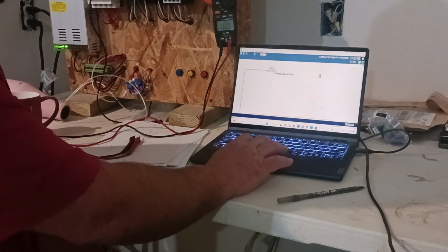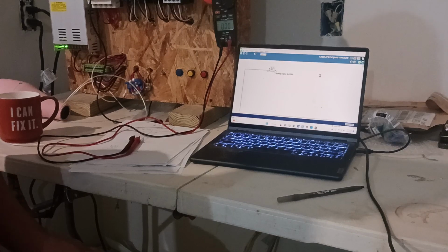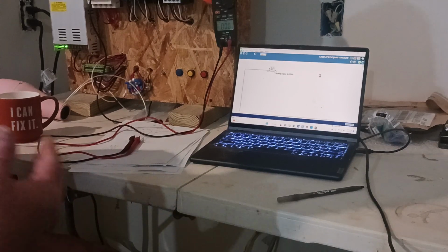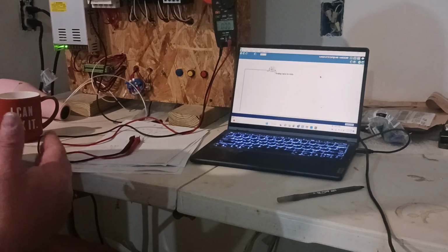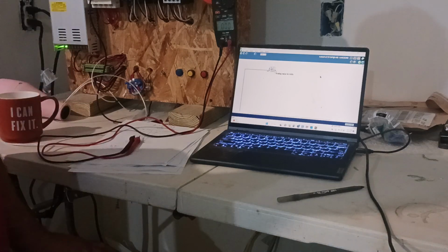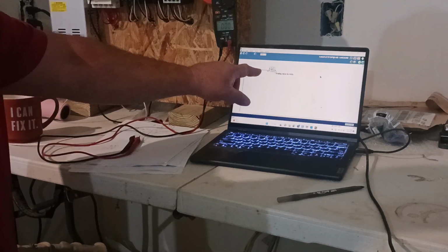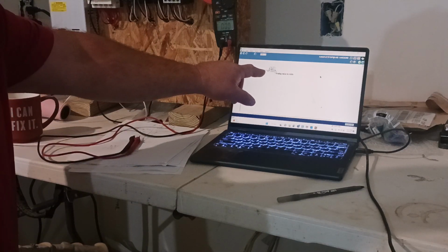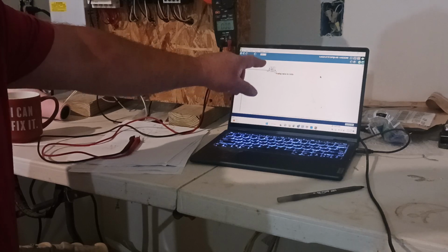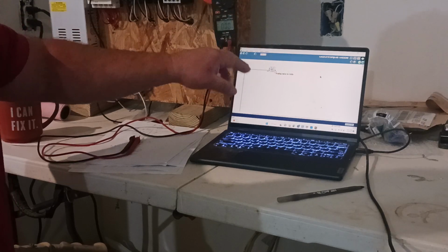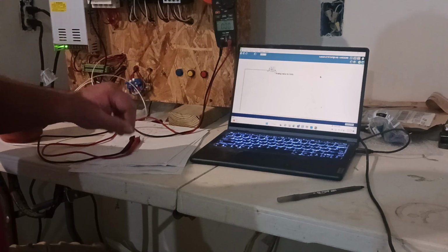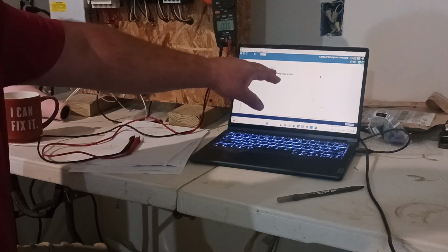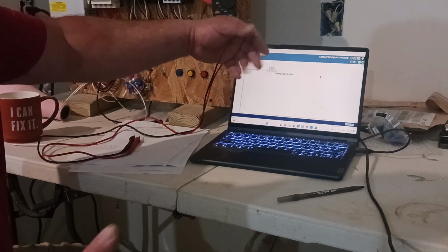I know that may not make much sense because I didn't explain it very well. I'll explain the equation a little better, but I just want you to get the basic idea that the highest analog value the PLC reads is 255, and if you take 10 divided by 255, you will get the number of volts. This only does it to the closest integer.